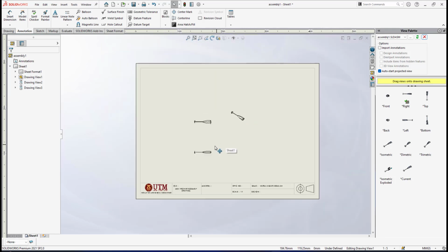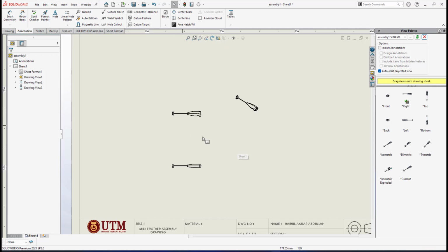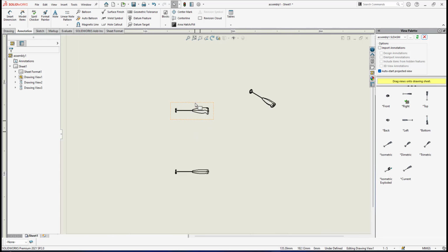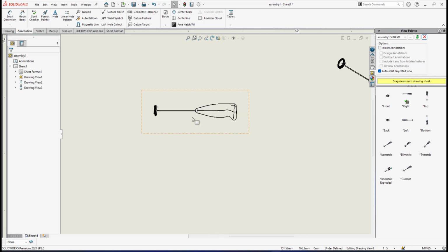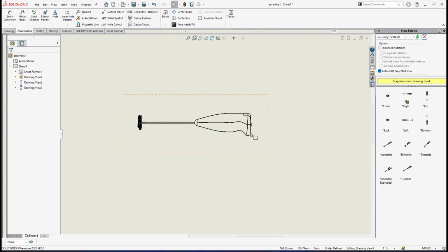Okay, the first thing I need to explain to you, and this is important because this is an assembly drawing, is the way you plan your assembly drawing. For my milk frother case, the milk frother is a full assembly. For example, in the plan view, some components are outside and already shown here, the steering rod. The top casing is already shown here, but the bottom casing is behind that, and also the other components like the batteries, the DC motor, the connector, and the bracket of this opening lid and so on are kind of hidden.